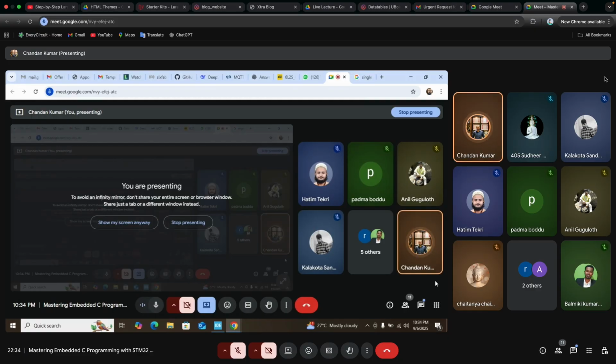Now the slave address, I have told you about this. The third one is the read-write bit. It is a single bit that indicates whether the master wants to read or write. I2C performs both operations, it can read or it can write. Who will decide it? Obviously the master will decide. There is one bit, the read-write bit, that decides whether the master will perform the read operation or the write operation.